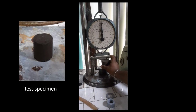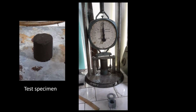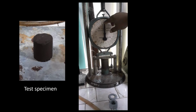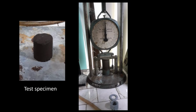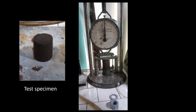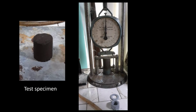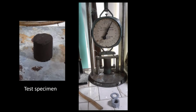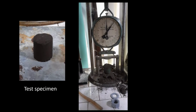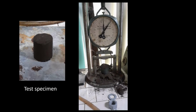Then the same sample is used to measure the green compressive strength. Place the sample on the sample holder of the spring balance machine. Then we rotate the hand wheel in a clockwise direction until the specimen collapses. Then you can read the strength of the specimen. Follow the same procedure for the remaining 4 samples also.